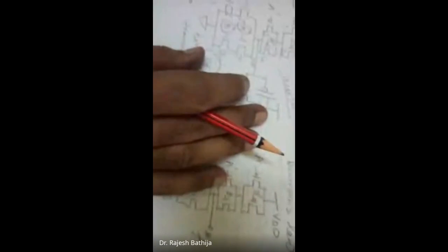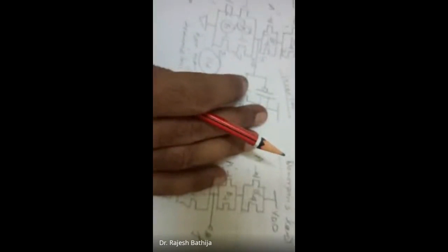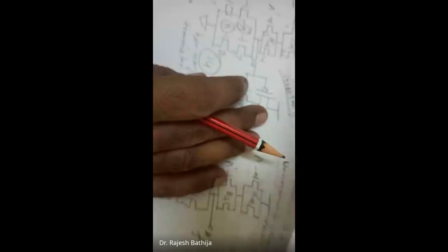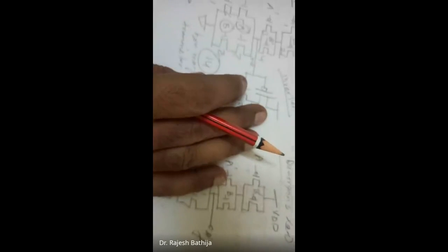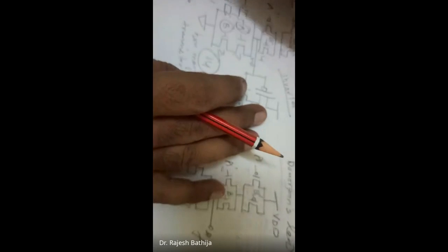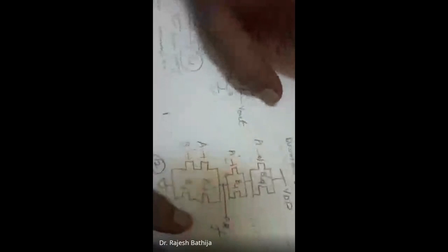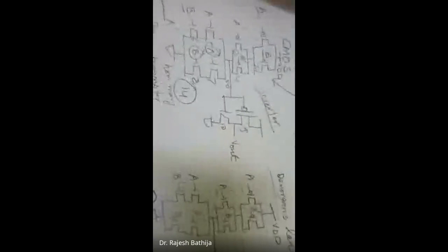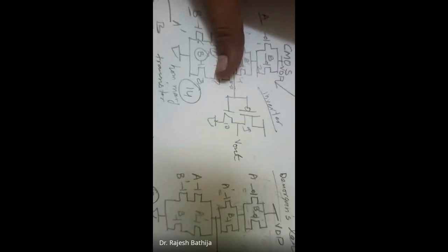In some expressions, the inverter gives fewer transistors in the CMOS topology. In others, De Morgan's is better. So you have to take care in design. Whenever we design any system, the prime concern is the area, and area is decided by the number of transistors you are using, as well as the technology we are using.